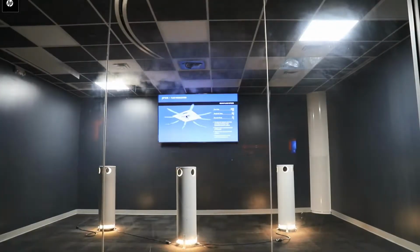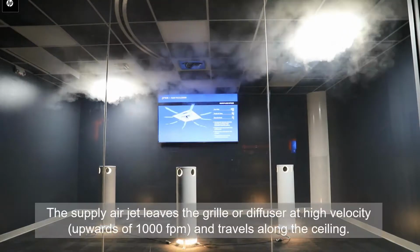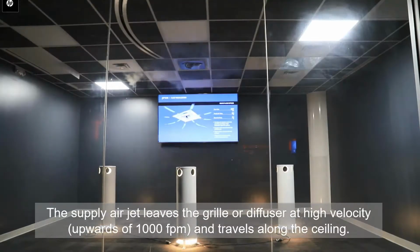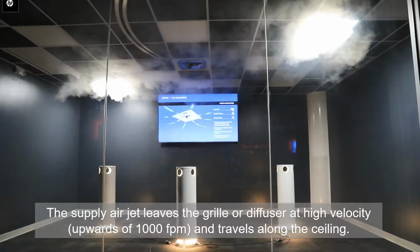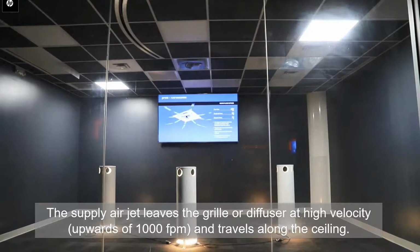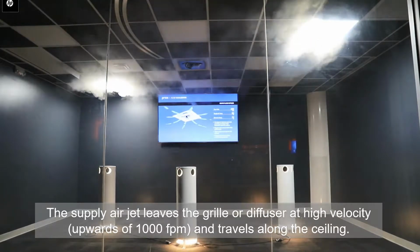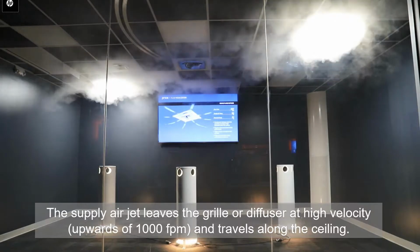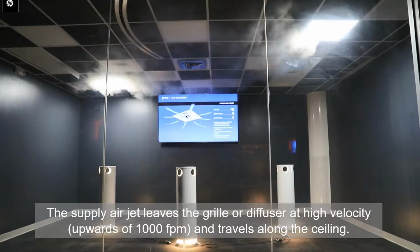Here's a larger view of what's actually happening. We'll go through this step by step. We have our air that enters the space from our air outlet, usually a ceiling diffuser such as this. The neck velocity at the air outlet can be anywhere between maybe 300 and up to 1,000 feet per minute. The higher the neck velocity, the further the air will travel, but also the more noise it will generate.